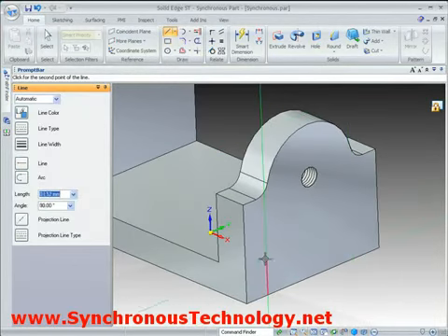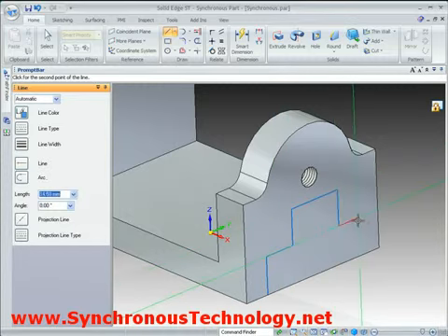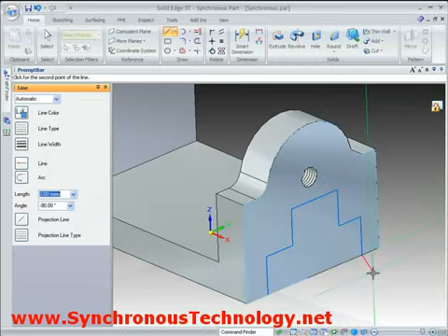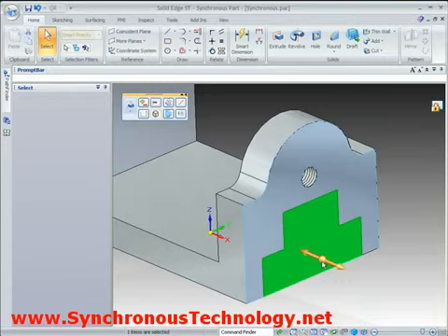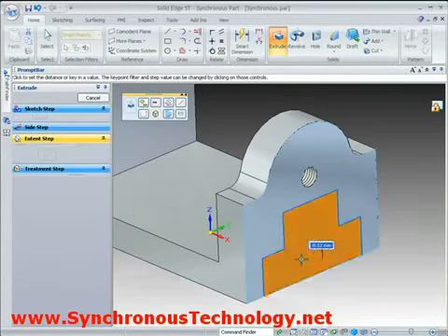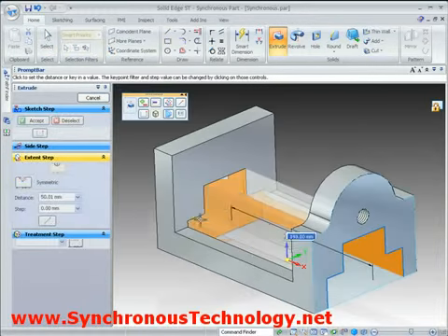Finally here, we need to create the slot through the middle of the part. Again, sketching directly on the inferred face and adding appropriate geometric conditions to ensure the shape stays central and symmetric. Then selecting the region, if we pull away from the model, it will add material. And if we push it into the model, material will be removed.